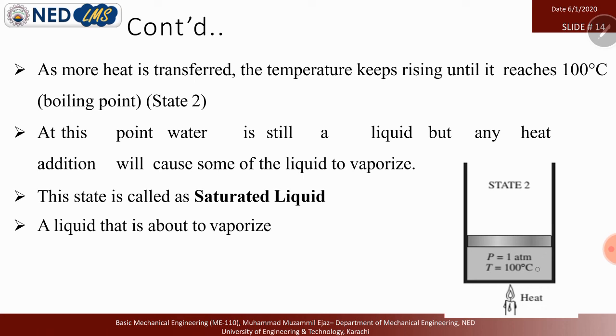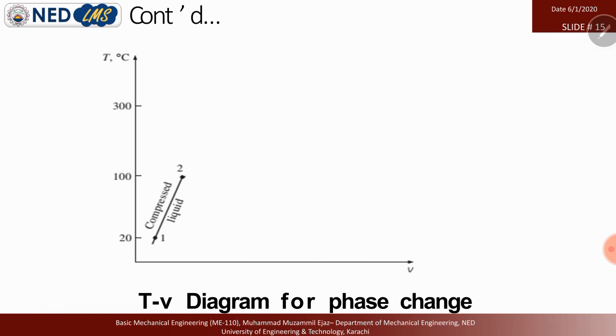You can do this experiment by yourself. You place the water on the stove and heat it till 100 degrees centigrade. The flame temperature is more than 100 degrees centigrade, but the temperature of the water is not exceeding 100. Why? Because the additional energy goes into the creation of steam. So it is basically a phase change process.